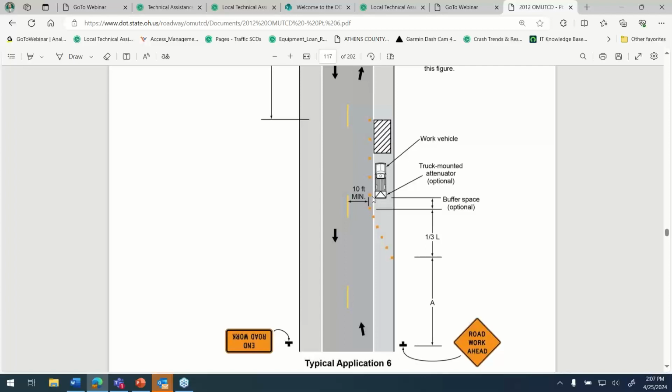And so we had a policy, we needed to think about, does that street carry commercial traffic, the big trucks or not? And so if it did carry the big trucks, we would not narrow it down any more than 9 feet.